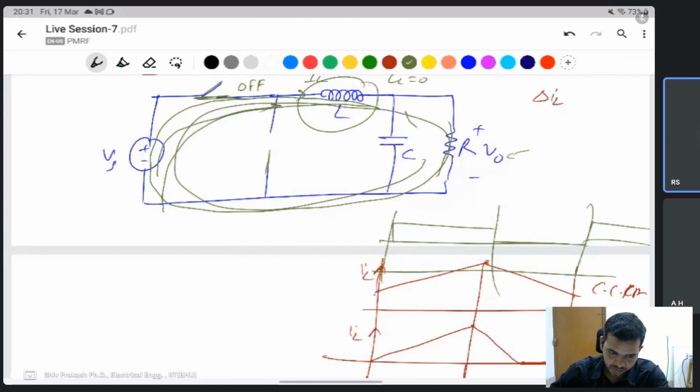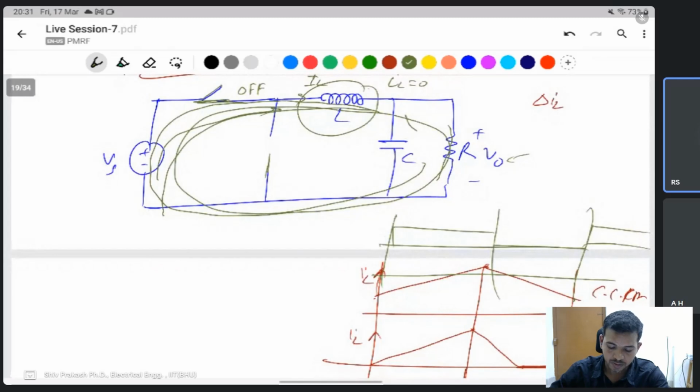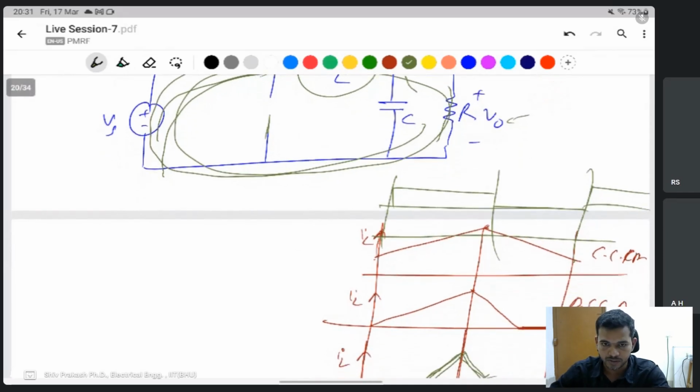Since this switch allows bidirectional current flow, the switch before the inductor that is connected between the top rail and the bottom rail is possible now. You have a MOSFET now, and a MOSFET has an internal body diode. If you take an IGBT or thyristor, then this is not possible; only this will work as a diode. The switch should be bidirectional, then only it is possible.